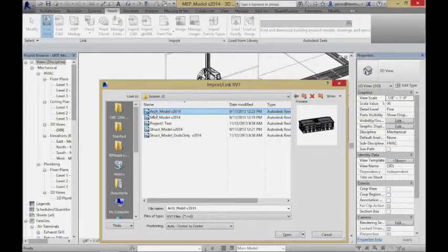There are so few cases where that is actually what you want to have happen, because as soon as in either model something's a little taller or a little broader, all of a sudden those centers don't match up. So rather than going center to center, what you almost always want to do is what I'll call origin to origin. We're in a shared coordinate system. Origin to origin says if your model was created with the XYZ 0 in a single place, and my model was created with the XYZ 0 in the same place, I'm going to bring them together so those 0 points line up with each other, regardless of how much geometry was created.